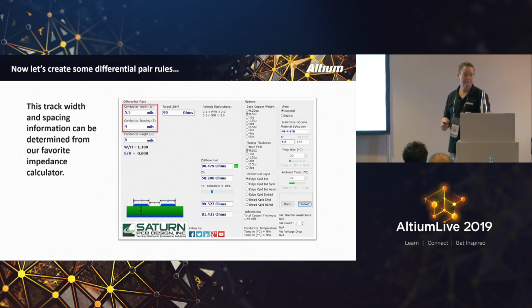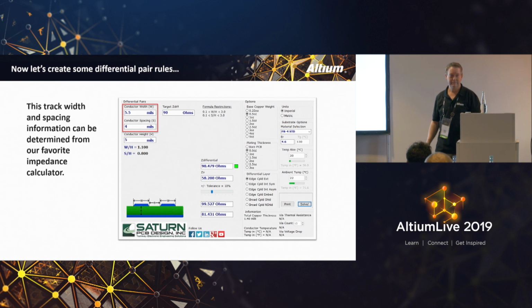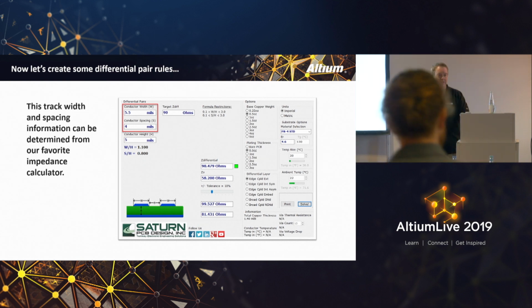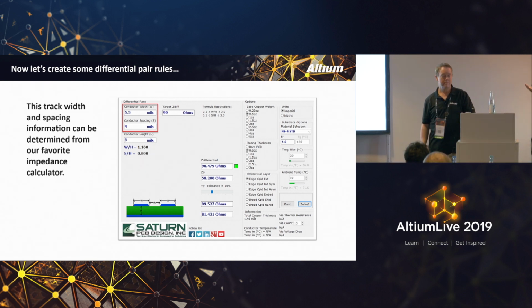So this is what I was saying in 19 with the impedance profiles on the layer stack. We included a field solver. Yes. So now in Altium Designer 19, you can do a lot of these calculations internally, and it will automatically do a lot of this stuff. So you can double check it if you want. We partnered with a company, Simbeor, to incorporate the field solver, but it gives you the same results. So, you know, I know engineers like to double check things.